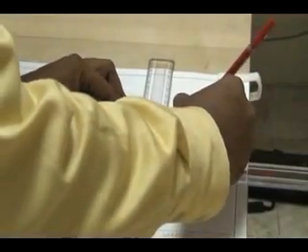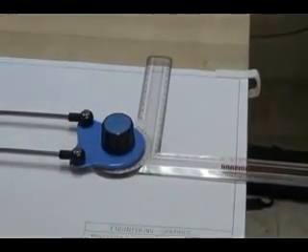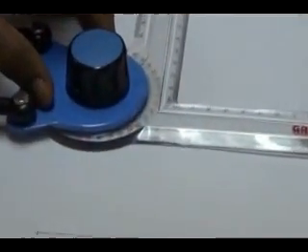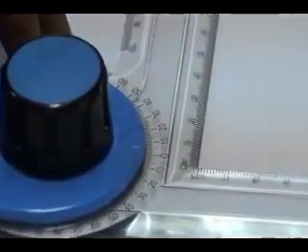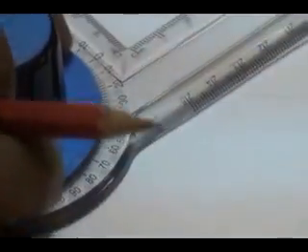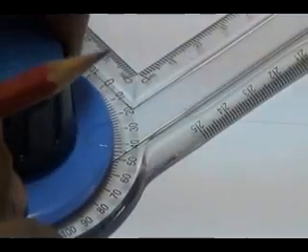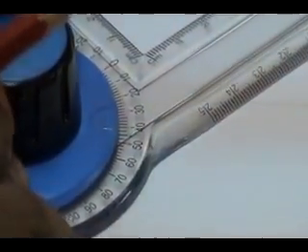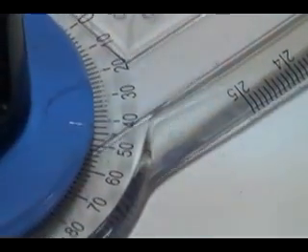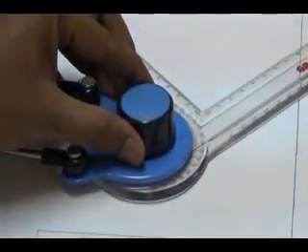I'm drawing a horizontal line. Once I have set to the reference layout line, I'm drawing a horizontal line. You see, I'm setting it to 45 degrees. With just a single setting of 45 degrees on my drafter, I can finish off this square. See, it is 45 degrees. 45 degrees means it is between 44 and 46, you don't have exactly 45. In between 44 and 46, I can fix 45 degrees. So the two scales of my drafter measure 45 degrees.